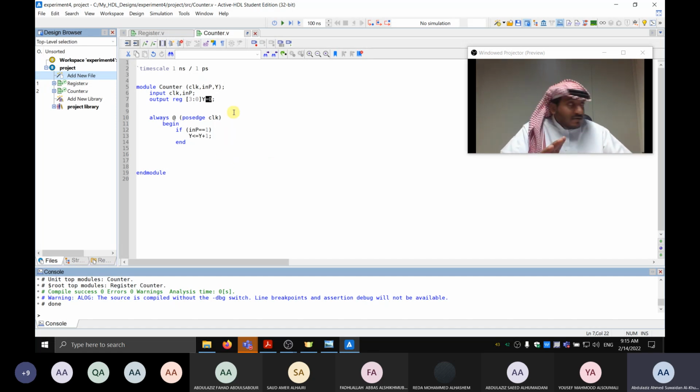Okay. Now we think that's everything, but there is also another issue with this one. We fixed the first one, but there is another major one. There is an issue here. Can anyone tell me what's going on? There is an issue with this code. No one? Okay, so all of you, reset. Yeah, if I want it. If I want to have a reset signal, you add another input, and then of course you make a condition. If that input is 1, y is equal 0.